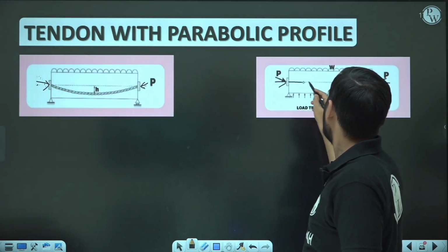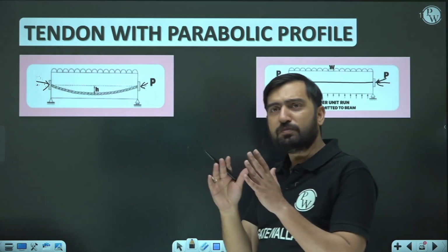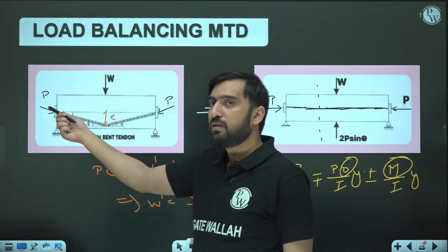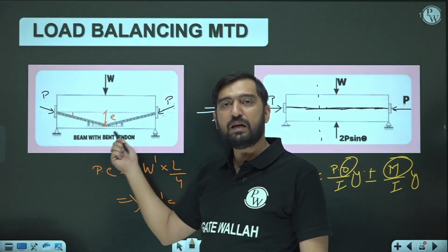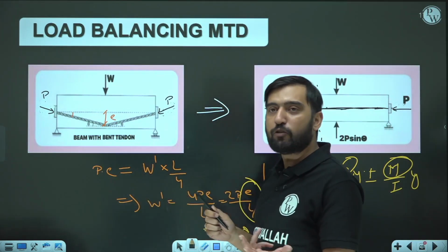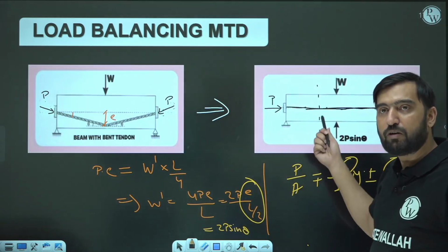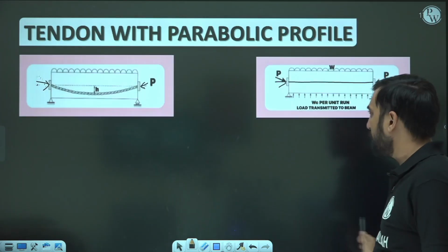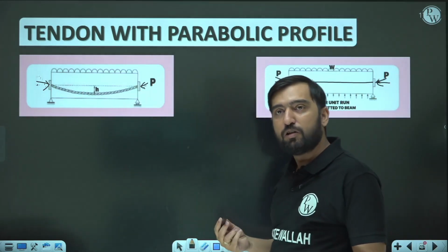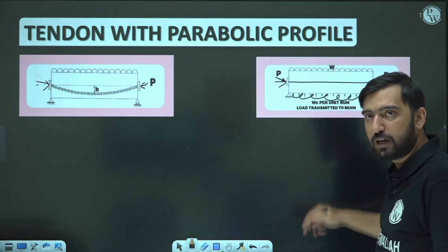This is my straight wire, and here, try to depict the bending moment diagram. Here the shape was linear. This linear shape of bending moment you will be getting from a point load, so an equivalency would have been developed in terms of point load. Here the shape is parabolic. Such a shape is the bending moment of UDL, so here you are going to get a value of UDL in the upward direction.